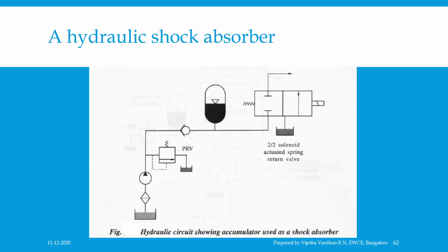This results in high pressure pulsation, creating compression waves at the source that travel at sonic speed upstream to the end of the pipe and back, causing an increase in line pressure. The high pressure rapid pulsation may damage the components used in the hydraulic system. These compression waves travel back and forth in the pipeline until their energy is dissipated by friction.